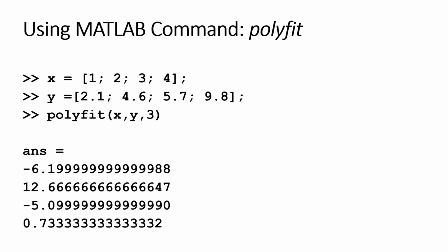So far, you have seen the manual approach to fit a polynomial equation through some data points. Now, MATLAB has a built-in function polyfit that can do the same job. The same x and y data points are used. Here 3 defines the degree of the polynomial, and we found the same coefficients as with the manual calculations.